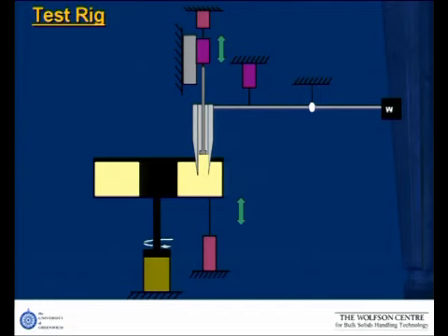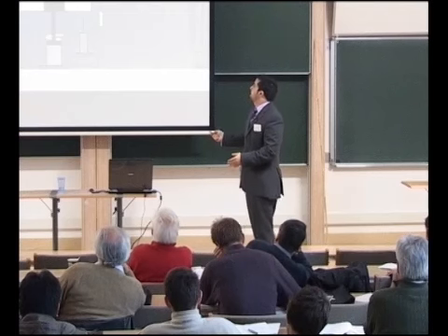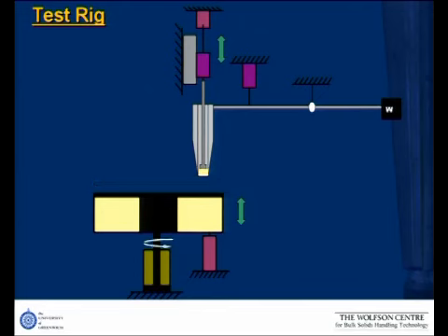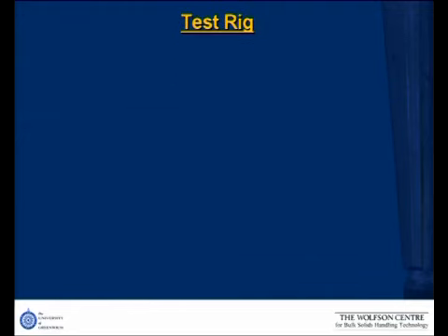So how it works: it comes up, and at this point where the powder is touching the body, it is sensing here, and sometimes sensing here as well, as soon as it's filled full of the material. And then if the powder requires it, you do a pre-compaction, but it's not happening all the time. And then the trough comes back, and there is a rotation movement, and then we are ready for the ejection. So we just do ejection and see what is the weight of the dose.